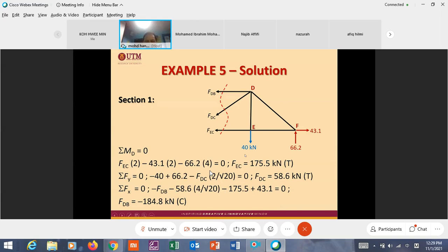So these equations are for the rigid body diagram, when you have equilibrium in X, Y, and also in rotation. When you say free body diagram, it applies to a joint and also to the whole structure. So take moments about D equals 0. Why do you choose D? Why not E?